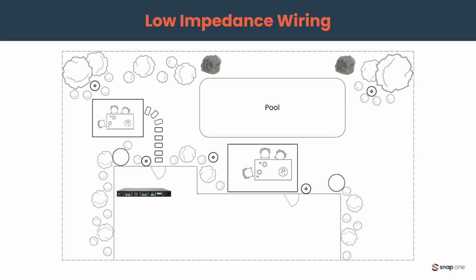If you have the option of doing 4 speakers in 8 ohm, or, I don't know, pick a number, 15 or 20 speakers in 70 volt, it's going to sound significantly better to have a more encompassing and encapsulating sound with 15 or 20 70 volt speakers than 4 speakers in 8 ohm. So I think when people ask which sounds better, a properly done system in 70 volt will sound better than a traditional 8 ohm system with fewer speakers.